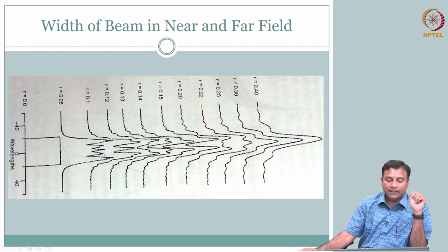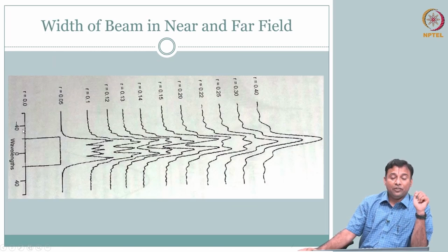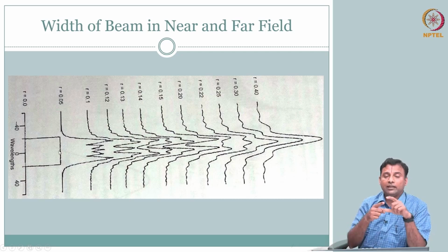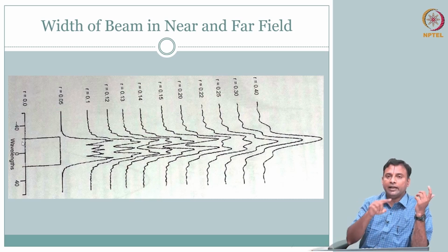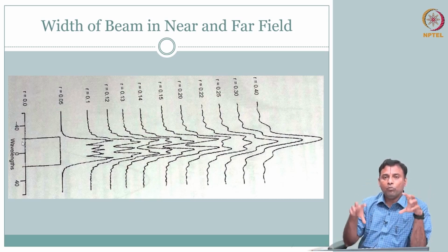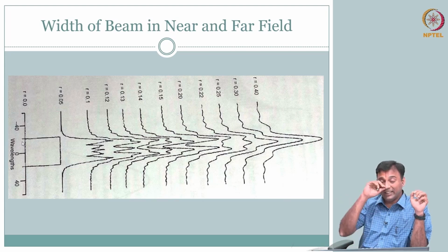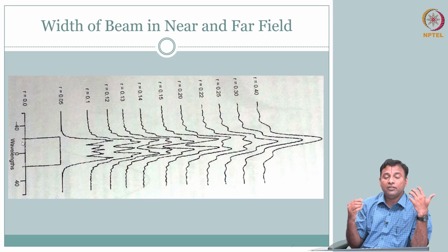One last aspect: if you have a rectangular transducer and you take one cross section, you have a hard transition, very similar to the windowing concept that you know from your first level signal processing course, when you do filter design. If you take a rectangular window, you will have more ripples. So, what do you do? You use windowing, Hanning, Hamming, you would have heard those terms.